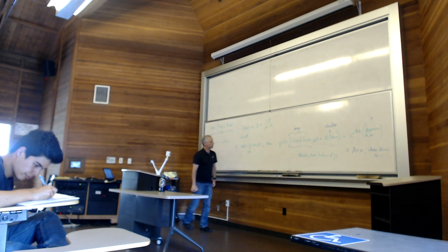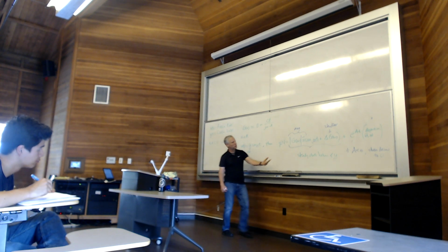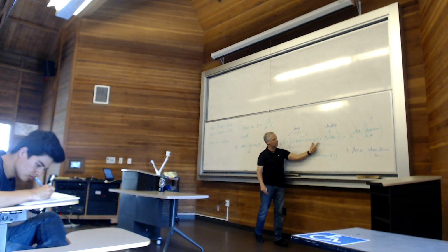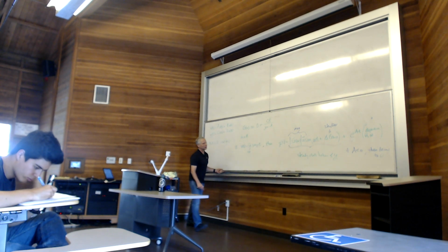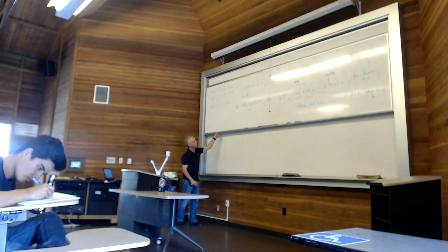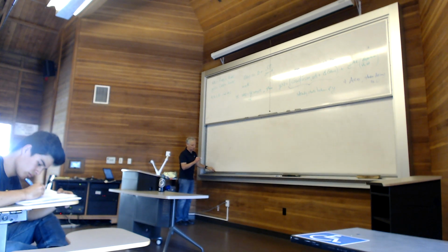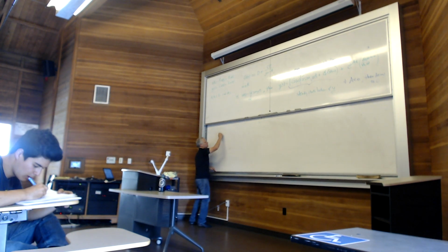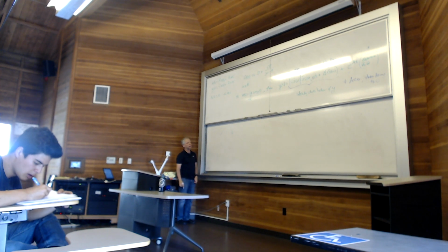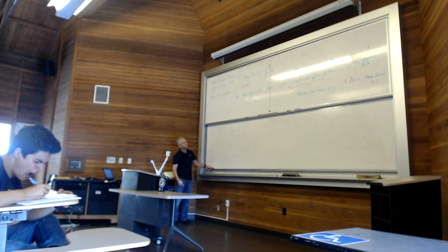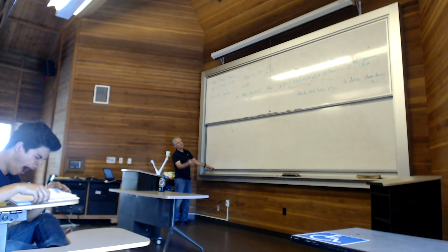Okay? So you put in a sine at a certain amplitude, you get out a sine at the same frequency, except it's not the same amplitude, it's been either attenuated or amplified by this amount, and it's shifted. Now someone came up to me after class, and this certainly came out of the discussion. We did this through a fairly circuitous route involving complex exponentials. But in the end, there's nothing complex about the input and nothing complex about the output. It's a sine, and what comes out is a sine. So this tells us how the system responds to sine waves.